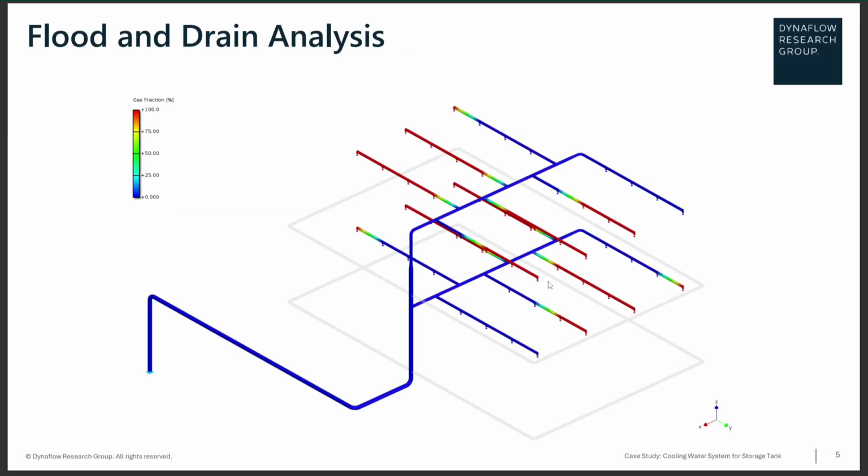And later on what we can do, and this is recommended mostly for dry systems, is a flood and drain analysis where we flood the system. As we can see, the blue represents the parts that are already covered by the water. In this case we are showing a given time in our simulation, and we can see how the system is flooded, and we can calculate the forces with this.